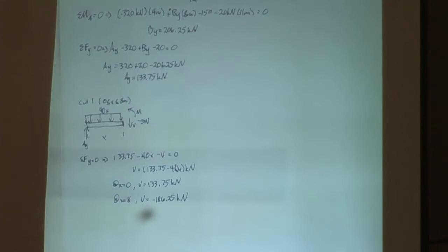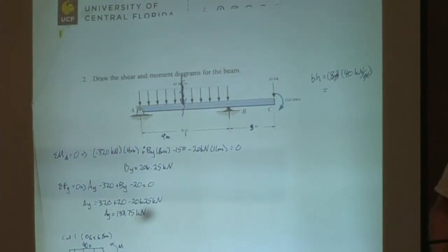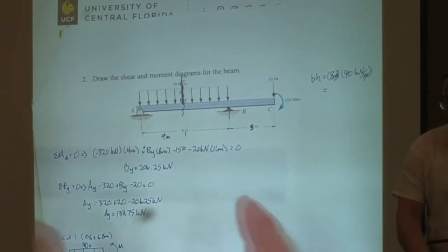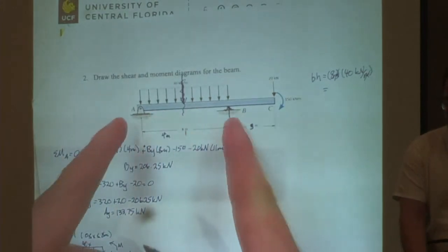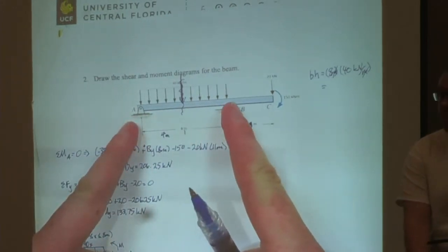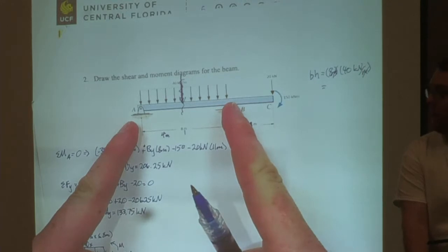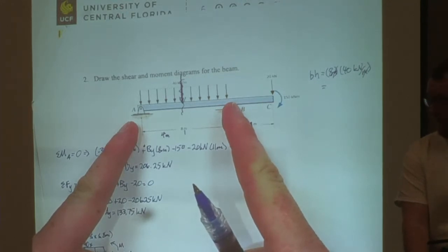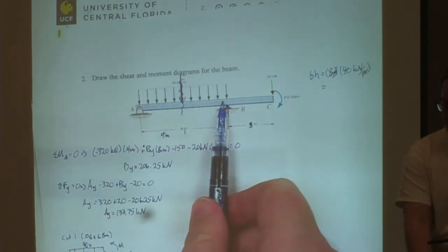So we can just set x whatever we want. Well, the reason you make your cut is because you're pretty much saying that it's an x variable throughout. So you have to make an equation for the line of the shear graph. It's a way of conceptualizing it. You can break it up into sections, right? You can make the cut here, but you realize that your equation for this entire section is going to be the same. So you're making an equation for every change in the beam. Does that make sense? Yeah, so your line's going to be different here than it is here.